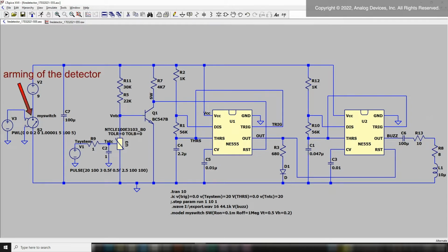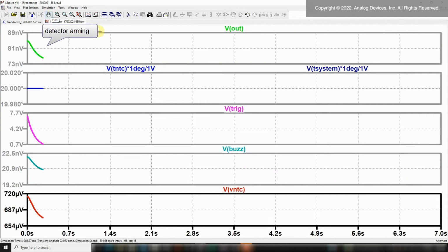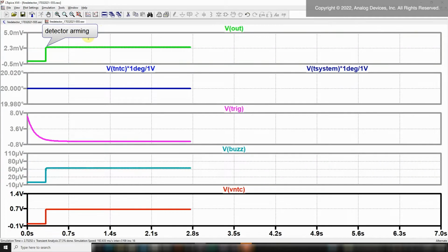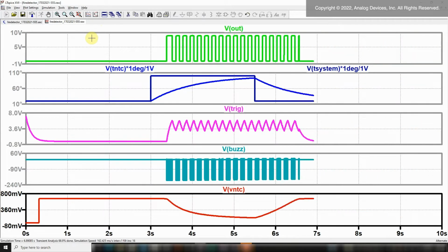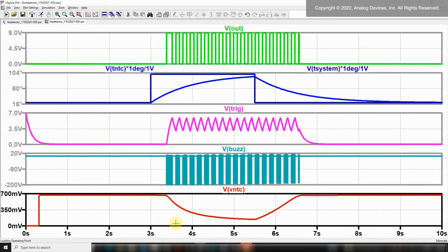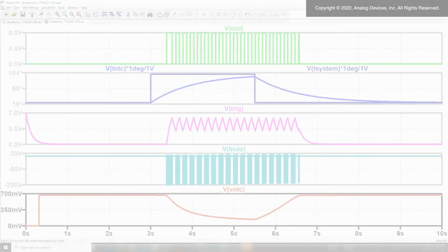We set the fire alarm circuit on with the start switch. We apply the temperature step and watch your ears now. It's over. Hopefully it was a false alarm. You see and hear that the noise stops when the NTC temperature goes back to a normal value.